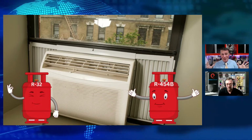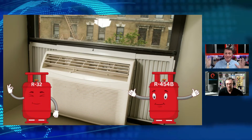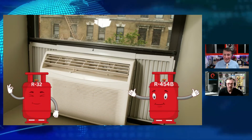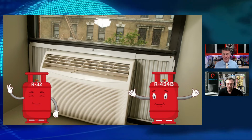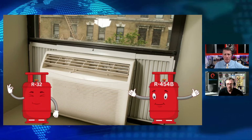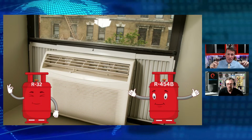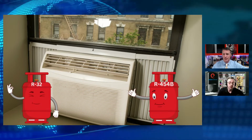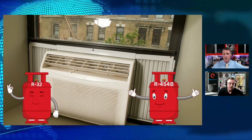So our commercial refrigeration folks, they're going to be all over the board, depending on where it's installed and what temperature, what application, what building classification. What's my evaporator temperature? Is this for a floral cooler? Is this for a dehumidification application? There's going to be a variety of different applications and refrigerants, whereas what we currently are comfortable with on air conditioning is really just going to be R32 or R454B. That's about it. I'm going to point out that R32 was approved for use in window units like we see here on the screen in 2015. That's a great point.